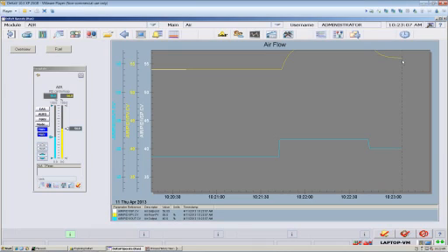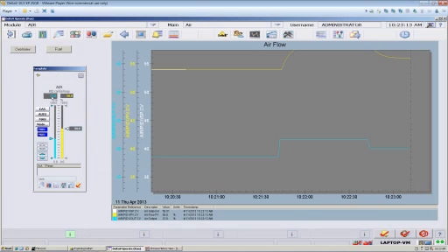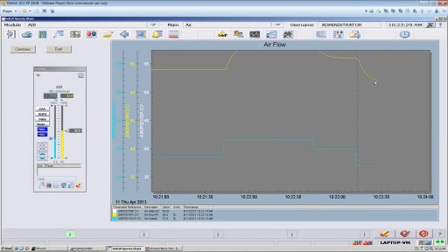Let's make a 3% step change down. Again, valve position change there. Flow starts to change here, 2 seconds of dead time. I can already tell my flow is leveling out, and it looks like it's going to come to a new steady state. It is the type of self-regulating model we talked about.